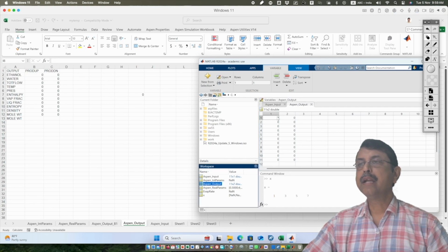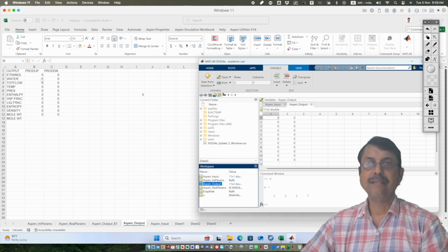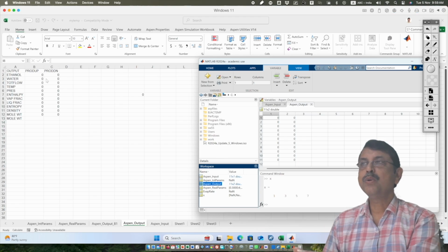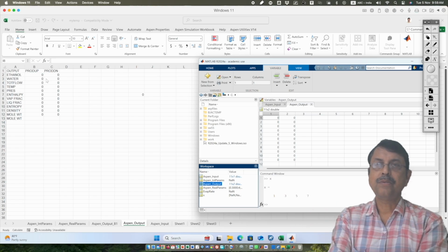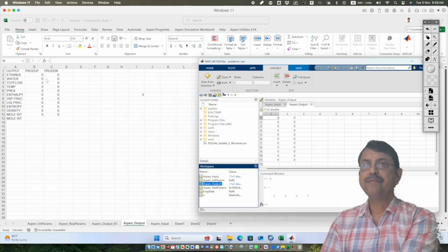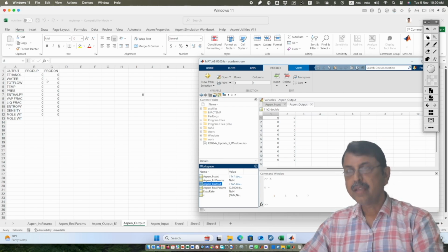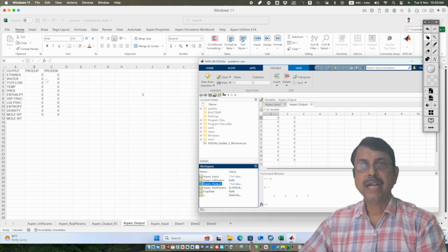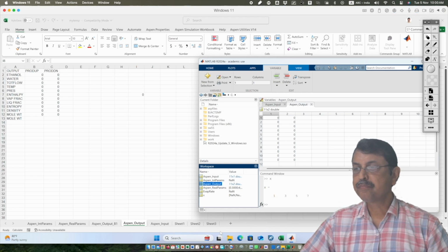See, all Aspen output has become 0 because you have redefined it. So all the equations have already gone. So whatever you give in Microsoft Excel, MATLAB is able to obtain everything because you have attached the spreadsheet link. So that's how you connect Microsoft Excel with MATLAB.